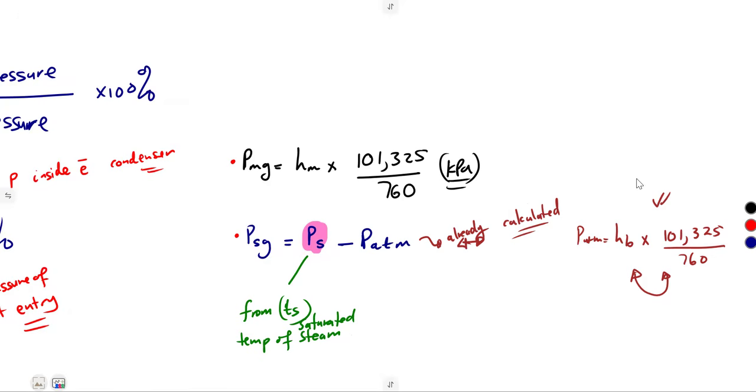And remember about this type of steam that we are talking about from all the calculations we had before. We cannot have superheated steam. That is the limit, where I was saying if we are dealing with our condensers, we are limited about the type of steam. We're not going to be using superheated steam. You see, the condition is here. PS cannot be from superheated steam. It is saturated steam.